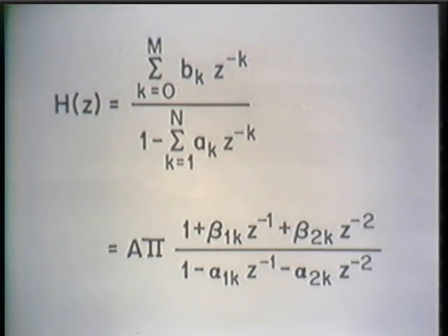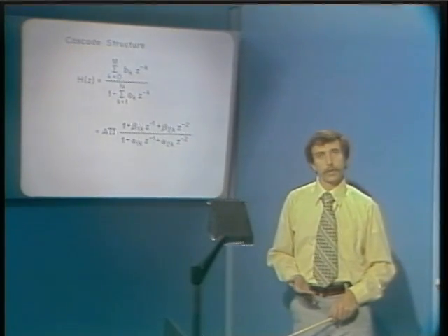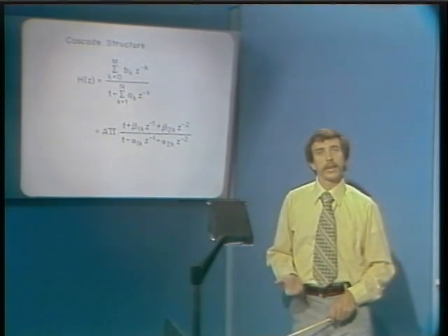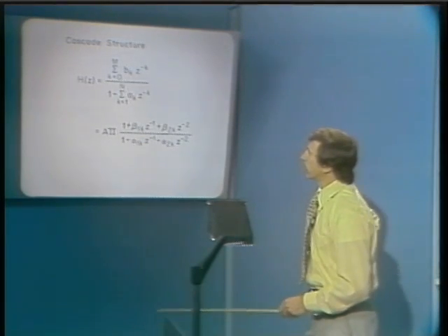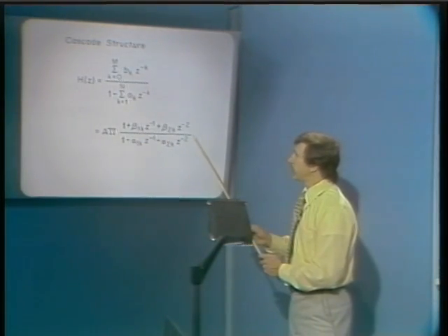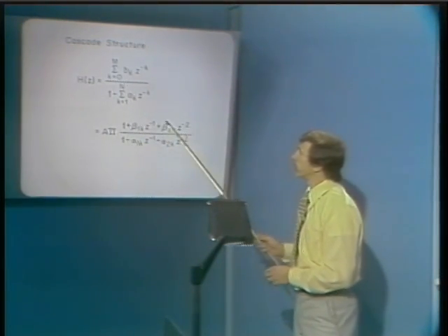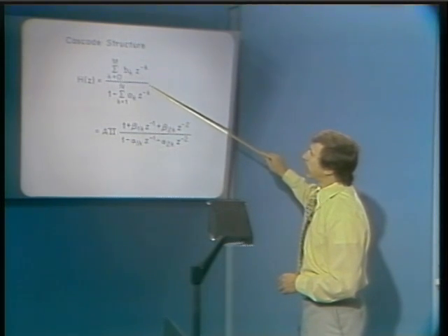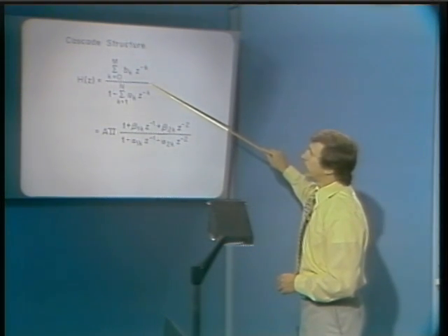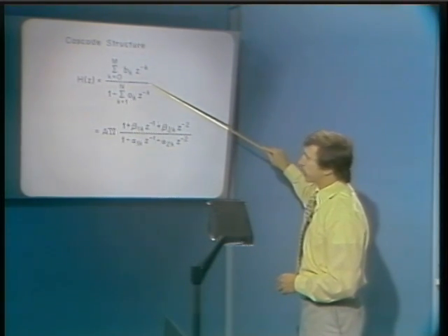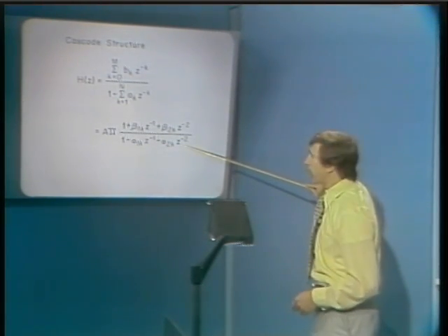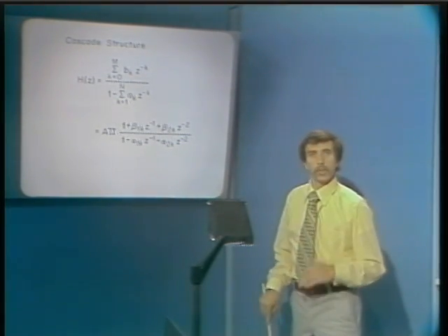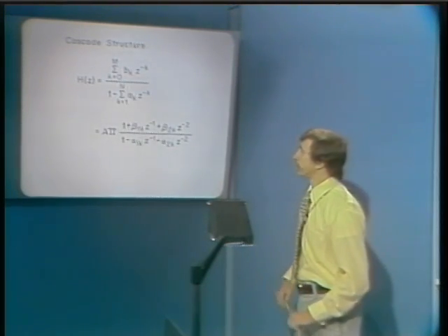That is, basically, the sensitivity of pole locations to errors in the coefficients is higher the higher the order of the polynomial. Consequently, if that indeed is an issue for the filter implementation, then it is better to implement a system as a cascade of lower order systems or lower order polynomials than as one large high order polynomial.